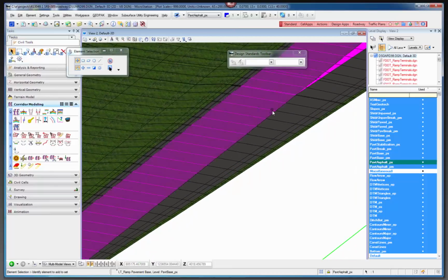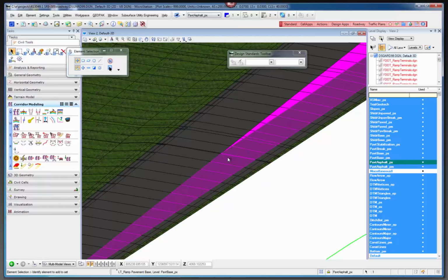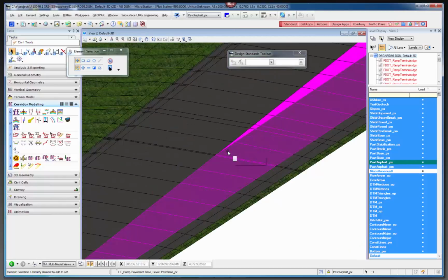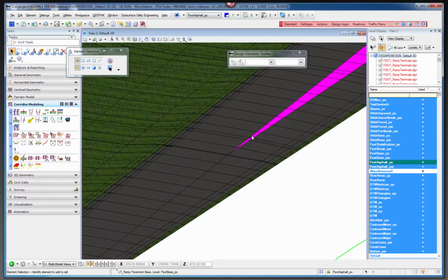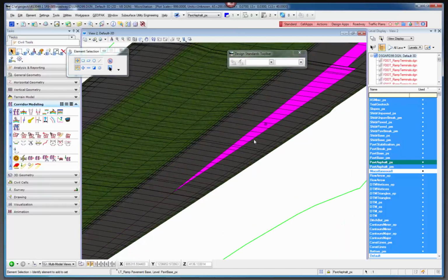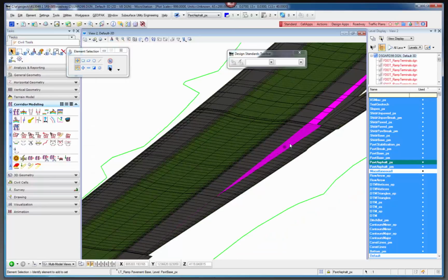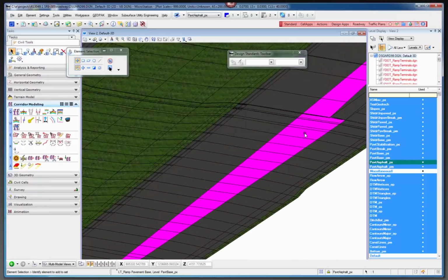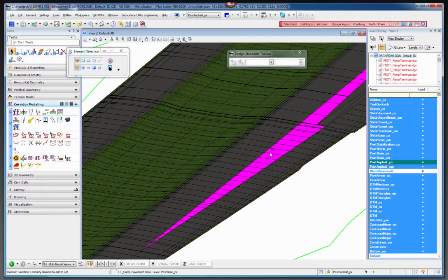And then as soon as it gets to the 12 feet mark, it will actually start building the Gore area. And it's still, actually I can't remember if that's 12 feet. No, actually it's the 15 feet. So it's the full ramp width, that's what you're going to see. And then it will start to extend this, and it's showing up purple because I used that stabilization. And then it will basically follow that.